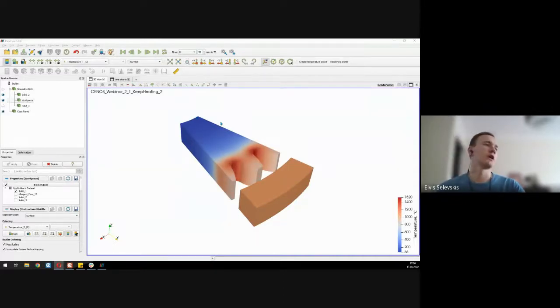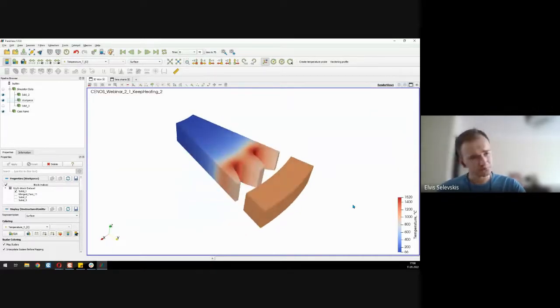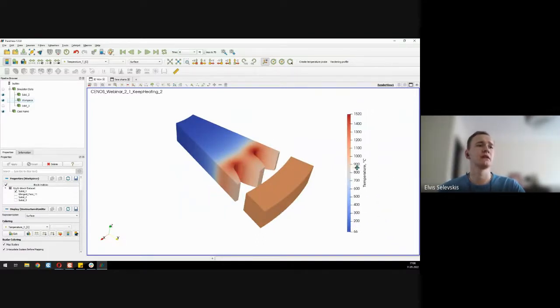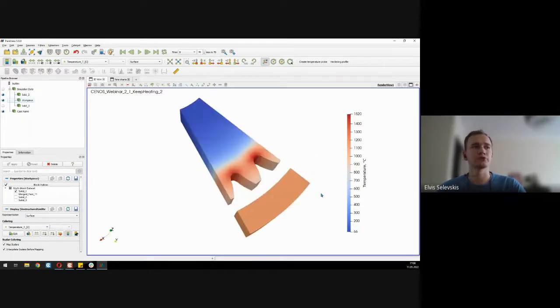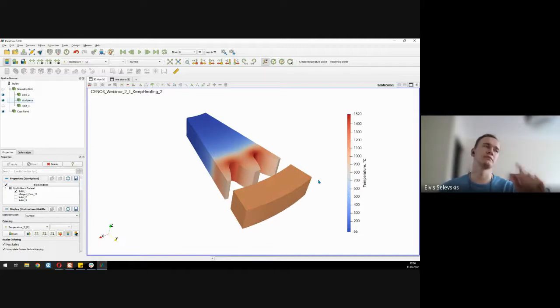Right now the heating has gone through. What we can see after the heating has gone through is the temperature scale next to it, where we can see the maximum and the minimum temperatures. One thing about these temperatures is that by default, they will be rescaled to the very last time step. This means at the very end of your heating, it will take the maximum temperature which it sees somewhere on the workpiece, and the very minimum temperature, which it also sees on the workpiece.